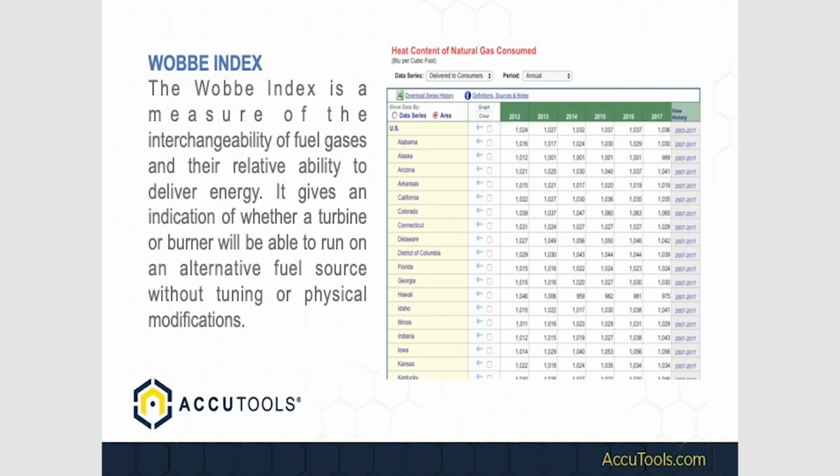The problem with this is, if you were to actually have a calorimeter, and again, CSA Labs went down there years ago, the heat content varies not only hour by hour, but almost minute by minute. The heat content of the gas is going up and down. So the big problem is if we don't set it up for average heat input, we don't know whether the heat content is high or low when we're adjusting that appliance. You need to make sure that you're setting it up clocked and get your average heat content for your area.